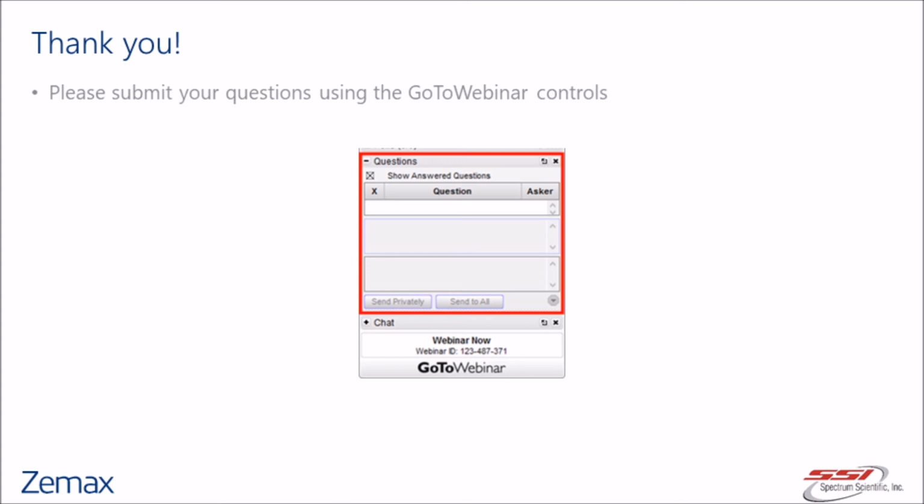There's a question here: what are the 6 degree of freedom constraints? Grant, you mentioned that the part has to be aligned in 6 degrees of freedom. Maybe you could elaborate a little bit? The question is, what are the 6 degrees of freedom constraints? So it's 3 laterals and 3 angles: XYZ translation, XYZ tilt. Those all have to be constrained during alignment.